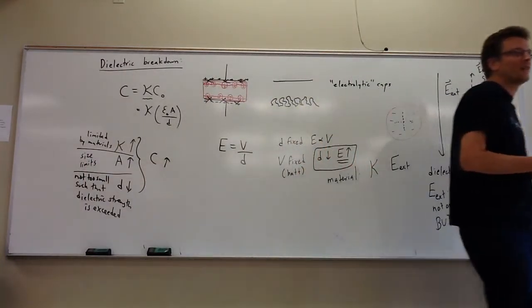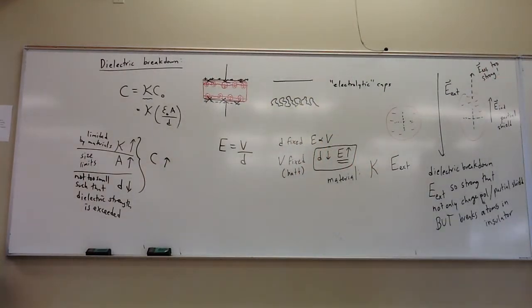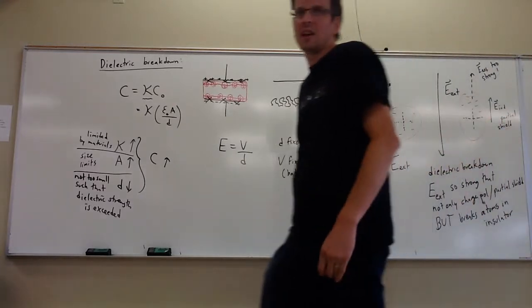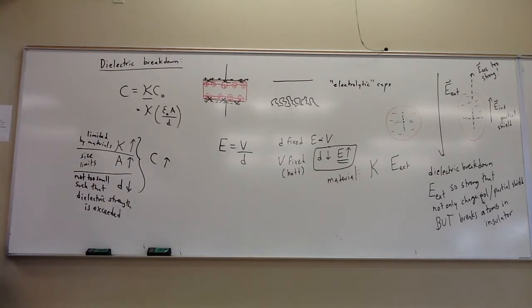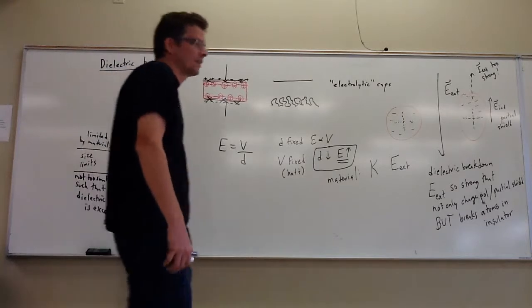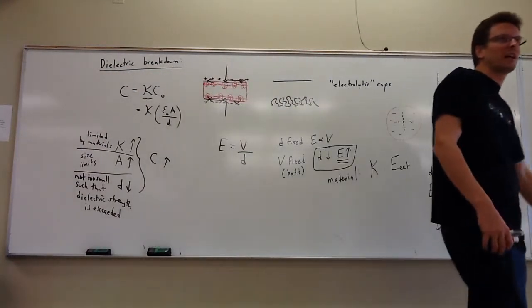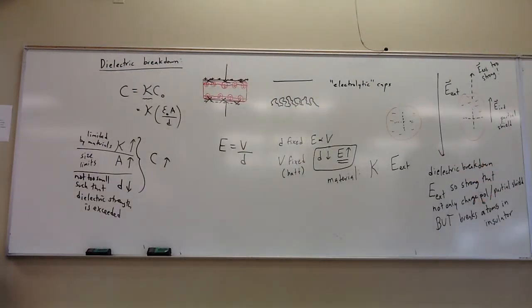And you will find that when you buy capacitors at the store, they will tell you not to plug this in above a certain voltage, because of course if you do that, you will zap the dielectric. And usually it's a permanent thing. It's not something where you say, oops, I'm going to unplug it and use it again.